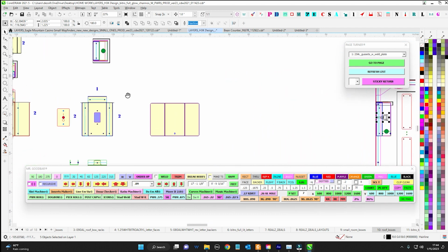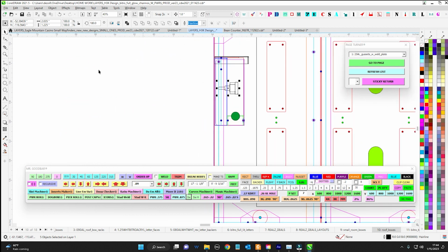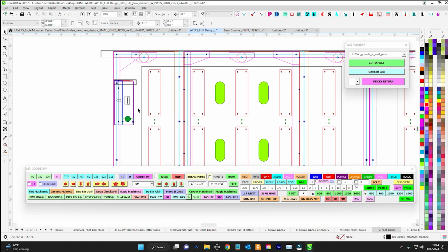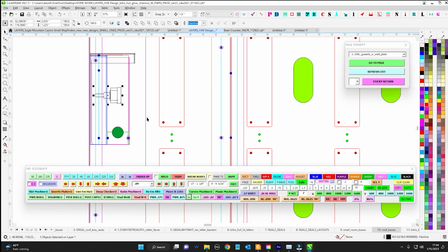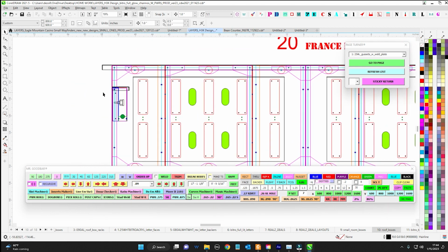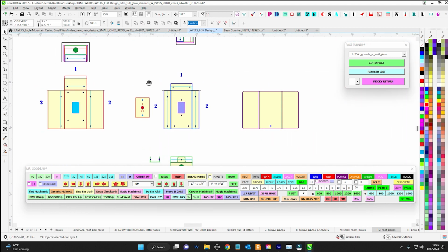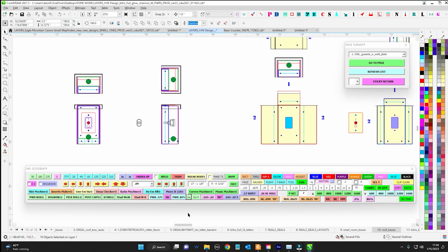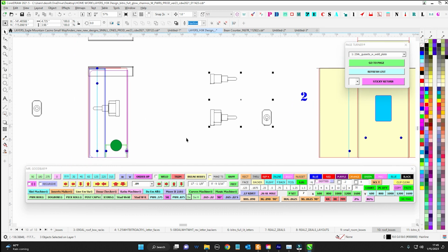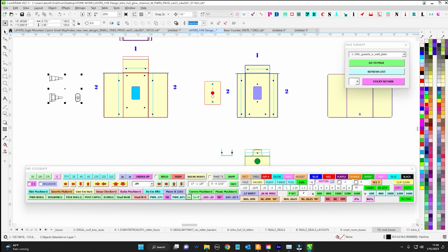So by creating a little box, we call it a birdhouse, that goes inside the thing here, because according to UL, water can't be present where a snap switch is. So if a snap switch is here, water can't be in here. But if you put the snap switch in its own enclosure that's not going to get wet, then you're fine. So we go this little extra step to protect the snap switch. It keeps UL happy. But in order to quickly lay this out, all I have to do is push the button there and I get a scale model of our snap switch so I can then use it where I need to.